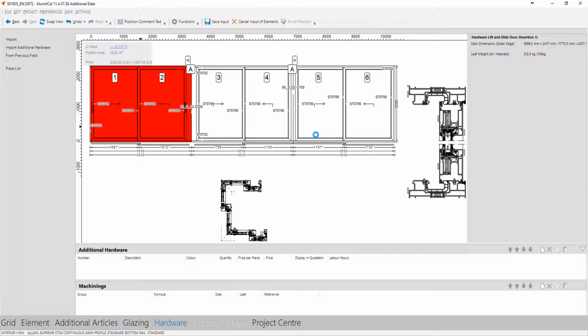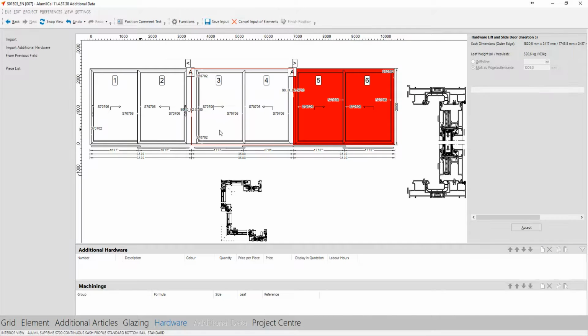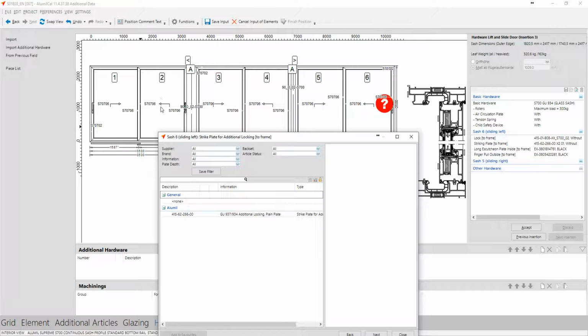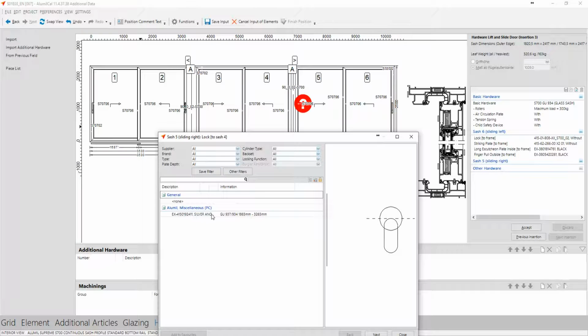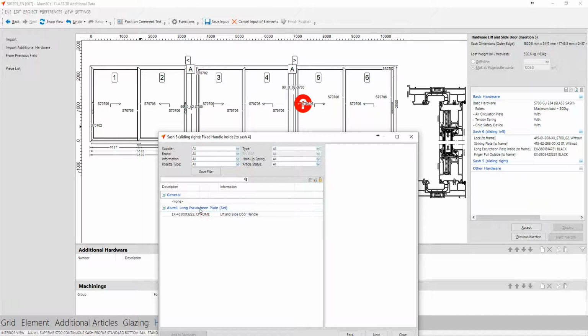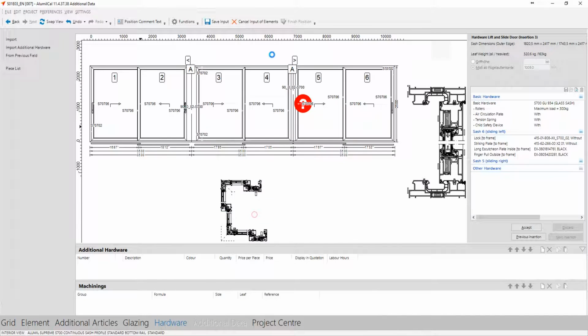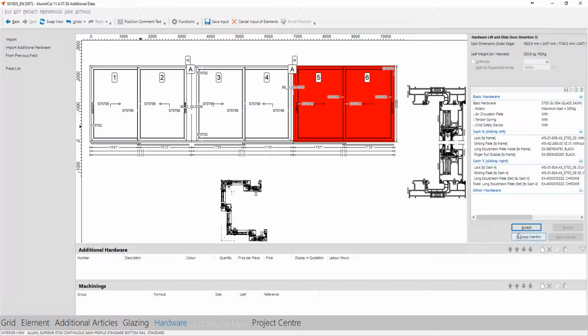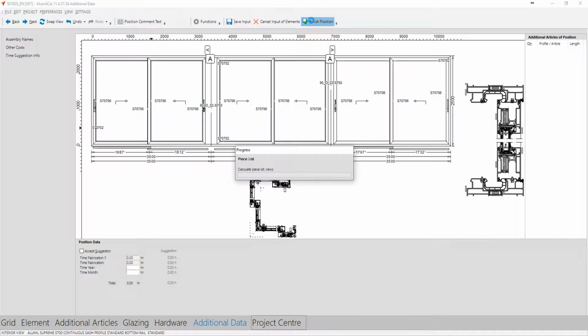Next insertion. Why we didn't put anything here? This is because we have this master and this master sash. So those two are the slave sashes, and the hardware was added together with the master, like here you will see. So this is for the master one, and this is for the slave one, for this one. So you don't need to select it here, you will select it on the master sash, on the master side. Next insertion. Finish, and voila, we have our 3-part corner construction.